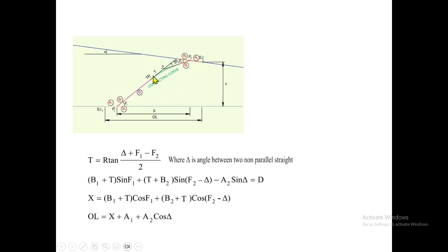For the hypotenuse of this triangle, here we know B1, that is a standard dimension. Yes, of course, if we want to have it, we can have it, otherwise we can make it 0. And this is a tangent length, whatever curvature we are proposing, and further we have to find out the tangent length. So further, we need to know the deflection angle here. How to find the deflection here?